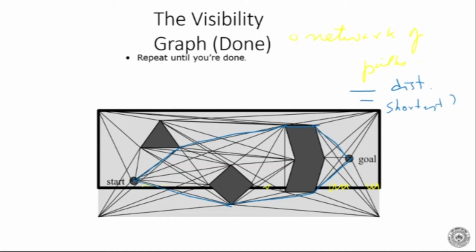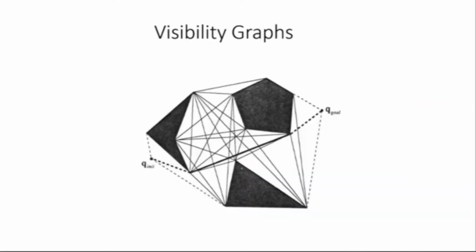Maybe. So this is basically called the visibility graph method, where we have drawn the visibility graph simply by connecting all the vertices by straight lines. It's like you go and stand on a vertex, and whichever other vertex is visible to you, you just connect it with a straight line. Now this is a visibility graph where we have drawn the complete graph.